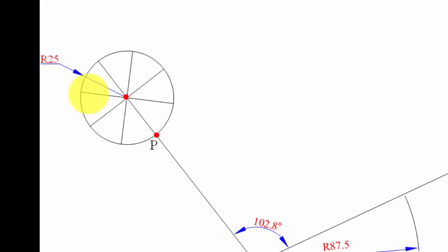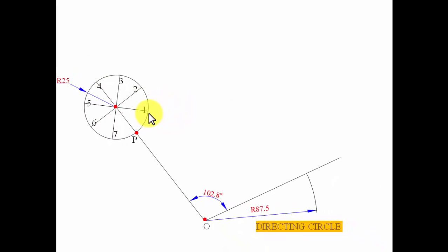Alright, fine. Now I'll do the numbering portion 1, 2, 3 in the anti-clockwise sense. There is a specific reason why I have done the numbering in such a way. Alright, now let's have the arcs with O as center and with OP as radius. I'm going to draw an arc right now, something like this.